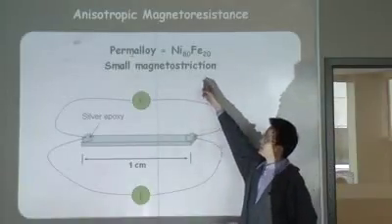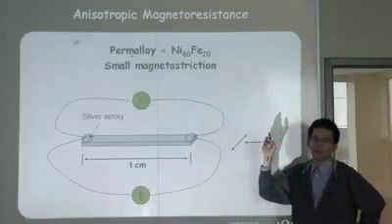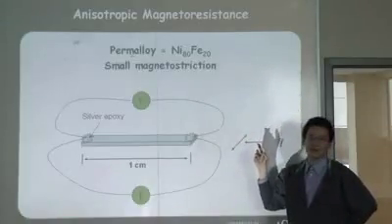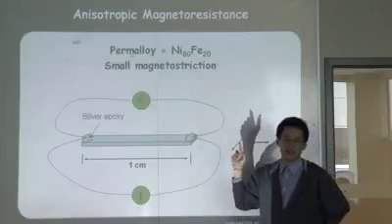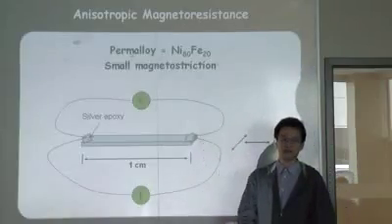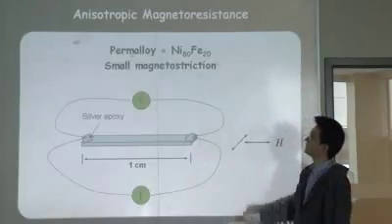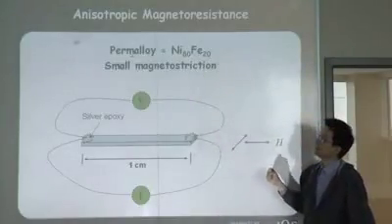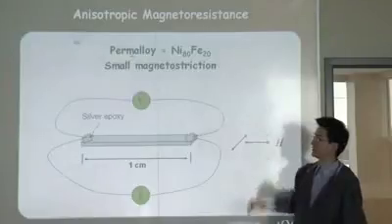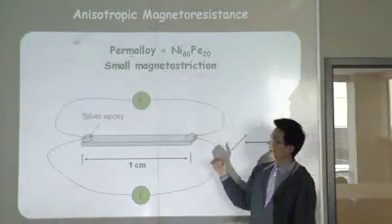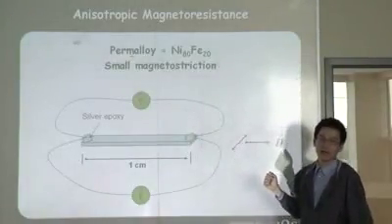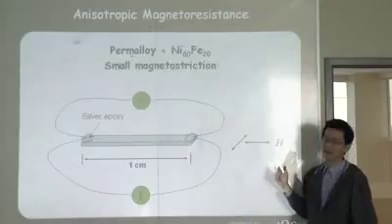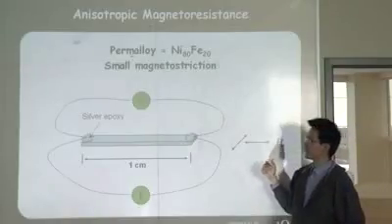The typical magnetostriction is actually not very large. They are like parts per million. But that is large enough for a large wafer. You get a lot of defects out of there. Therefore, people developed this permalloy. It essentially has no magnetostriction. Another nice thing about it, it has a pretty high AMR signal, roughly 5% at room temperature.